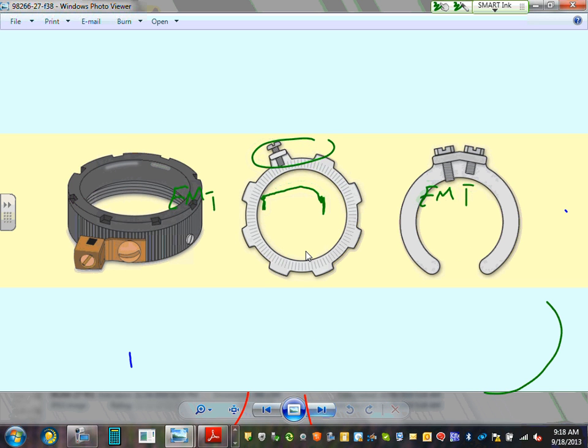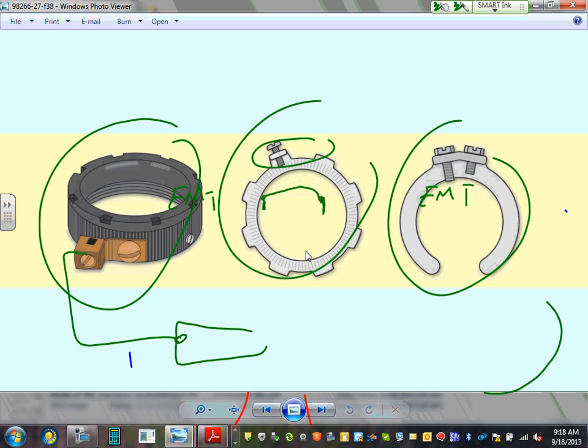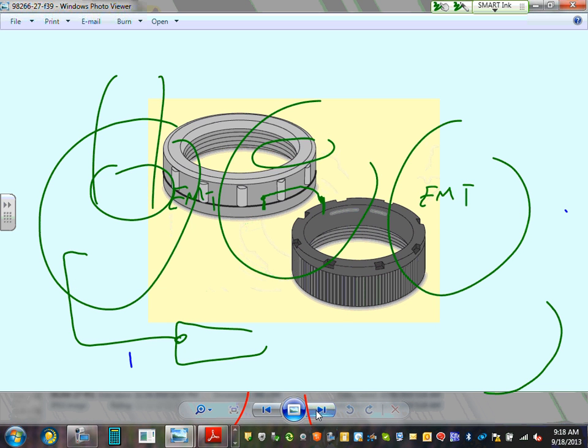Here are a couple of examples, guys, of bonding bushings and wedges. Bonding bushing here, and different types of wedges where you can bond the conduit itself. You take a wire from here, go to the ground bar, and land it right on the ground bar. And you put your conduits right in here. By doing it this way, now you have bonded your conduits. That's a major topic, guys. Again, I promise you, we'll hit it more when we talk about grounding and bonding.